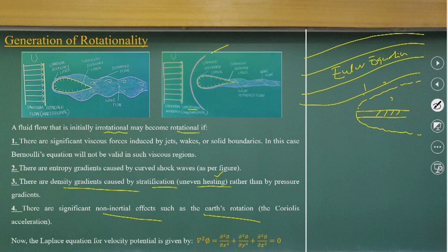But inside this is the boundary layer, where we will discuss more how to link these two conditions. Instead of solving the Navier-Stokes equations, we can solve the boundary layers and the Euler equations to solve the external flow field. But if you talk about any internal flow, for example pipe flow, you can understand it is totally viscous dominated.